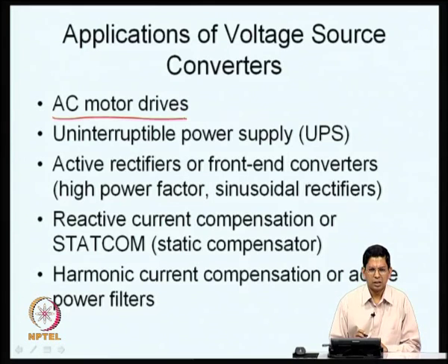An inverter is capable of giving you AC voltage of an amplitude and frequency that are programmable. So, you can get whatever voltage amplitude and frequency you want, and that is what is required in a motor drive, as we will be seeing shortly today. In fact, our emphasis today will be on AC motor drives. There are also other applications of a voltage source converter.